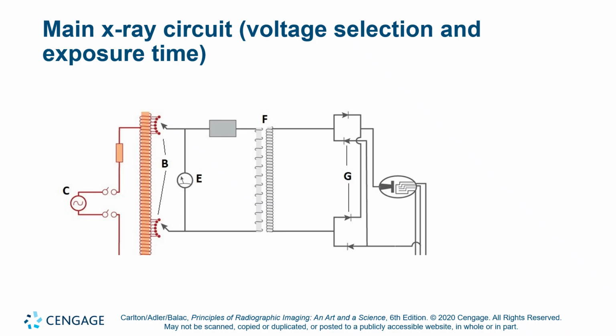And then if you turn that X-ray tube vertical, I don't know why they turned it sideways, that's the fourth rung of the ladder. So all of those are wired in parallel to each other. So the voltmeter is literally telling you the voltage at the voltmeter, but it's also telling you the voltage at the auto transformer, the voltage at the step up transformer, and the voltage across the X-ray tube.